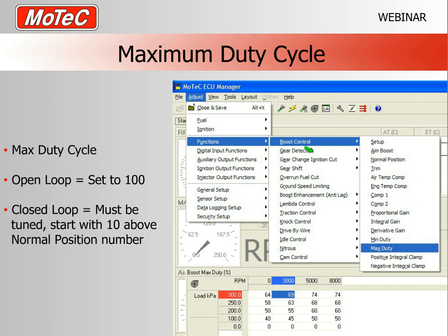But when we go to closed loop, when we allow the computer to make the decisions and potentially don't have our P, I, and D parameters right, you can have the computer calculating enormous numbers and the engine over boosting very easily. By clamping how much it calculates, we'll clamp the amount of the disaster, if you like.